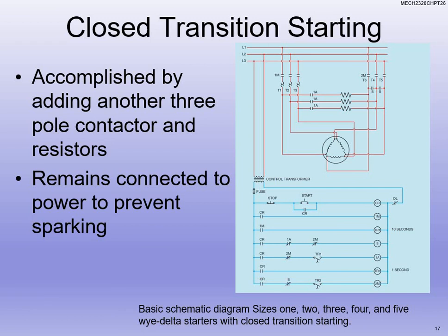We don't want to lose any power during that transition, so that's why we have to do this in our controls. Just like when we went from using resistors to stop the inrush current and reactance to stop the inrush current, we had to do the transitioning. So we have closed transitioning here. As it happens, we're using the timers to close that transition so that there is no loss of power, voltage, or anything as we go through all that.